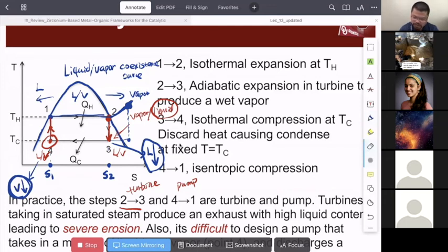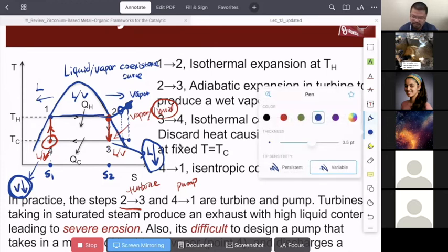So we want to make sure that we are at the right condition, so that when we move to state 3, we are quite close to the saturation point where we can easily ignore the component of liquid, right? So we claim that on this curve itself, we have the liquid vapor saturation, but if we slightly move this to the right, we are going to get rid of the last liquid drop. So if we are able to stay over there, that should be my best option. Okay, how about the next one? Well, the next one is also very similar to that sort.